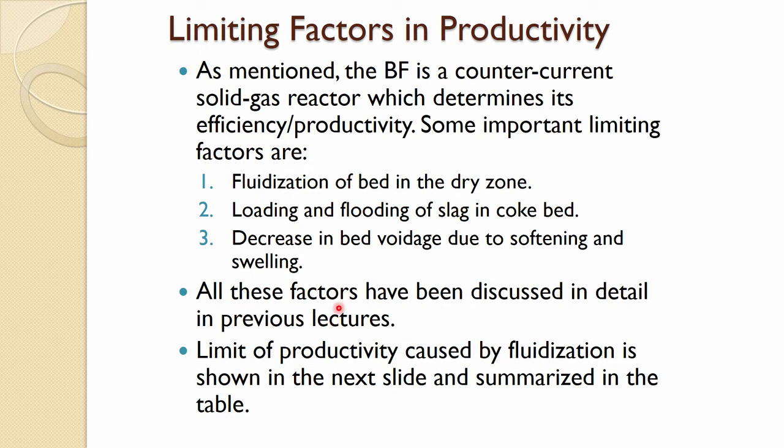So, there are some limiting factors in the productivity. As mentioned before, the blast furnace is a counter current solid-gas reactor, which determines its efficiency and productivity. Some important limiting factors are fluidization of the bed in the dry zone, loading and flooding of slag in the coke bed, and decrease in bed voidage due to softening and swelling.